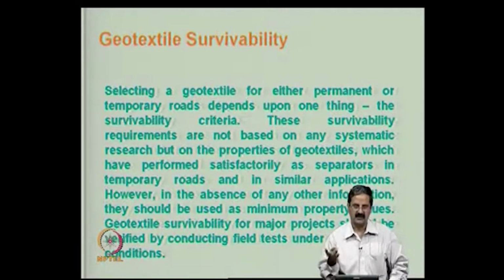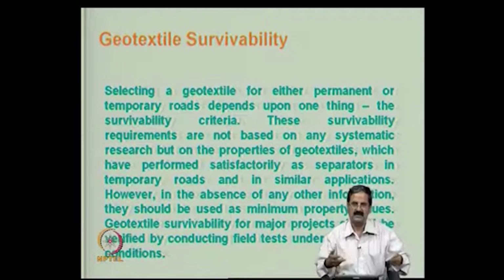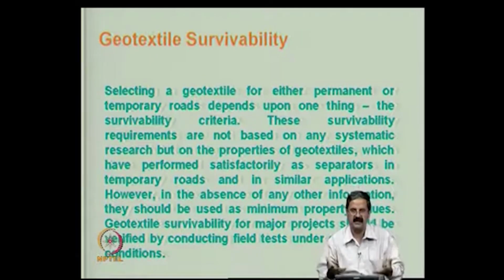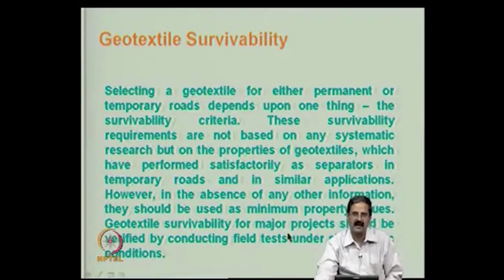And for separation, if you are only talking about survivability criteria, it is the handling stresses, like how much load it can take. If a big stone falls on it, it should not get punctured. So, what is the puncture resistance? Is it how many newtons, or what is the force it can take without getting punctured, is what we like to see. These are all by trial and error and then by practical applications and experience, and people have standardized these numbers for different applications.